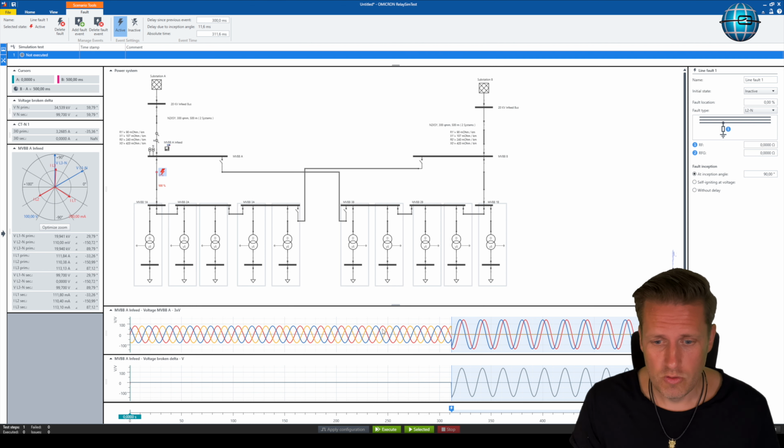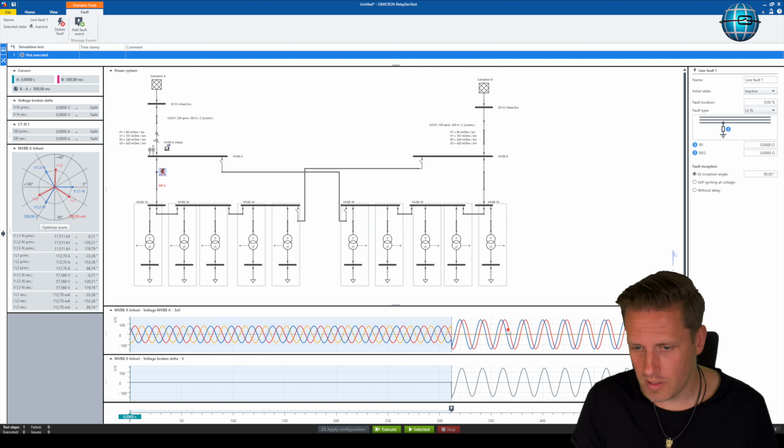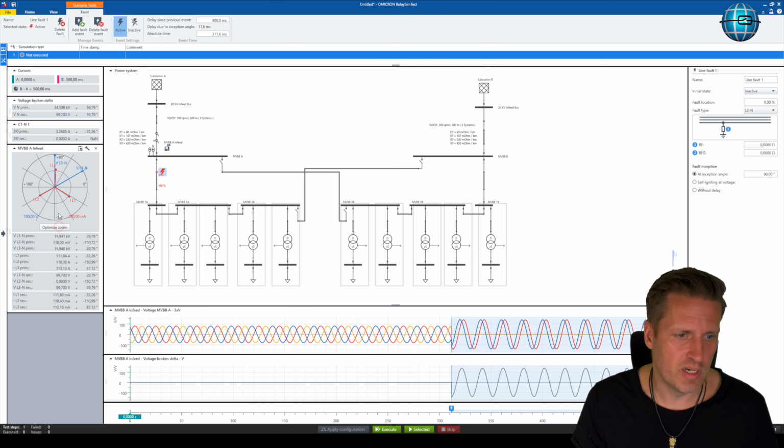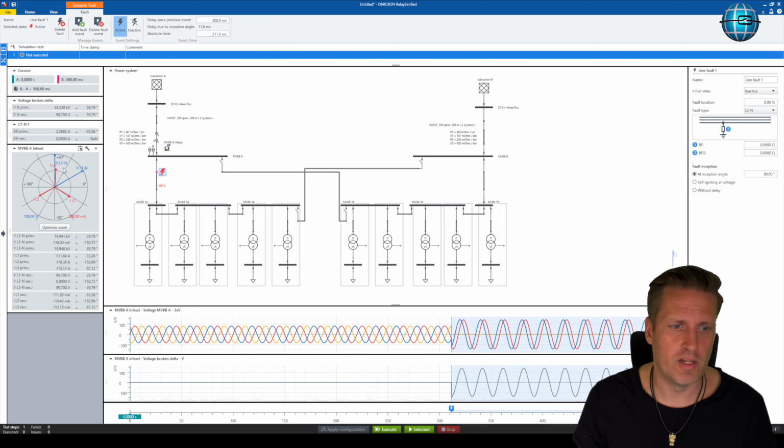Okay, and now you are able to switch here to the fault-free area, and you can also click here in this faulty area, and you can see how the phasor diagrams change just by clicking in these different ranges. Okay, and here we can see already that our voltage, the blue arrows are our voltage from phase 2, is broken down to almost 0. As we can see here, there are just a couple of millivolts still remaining.